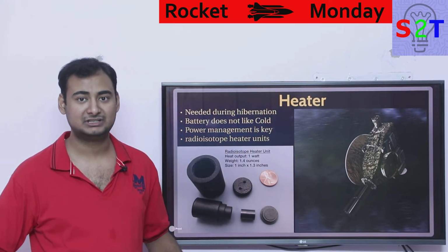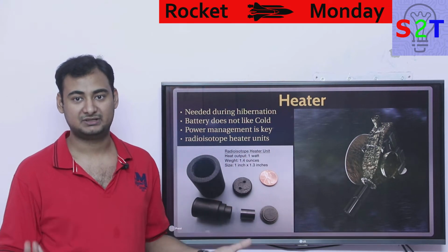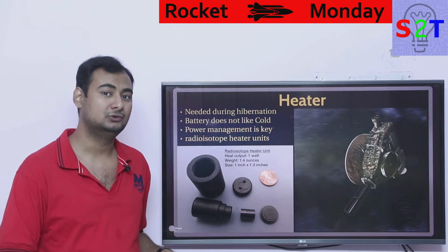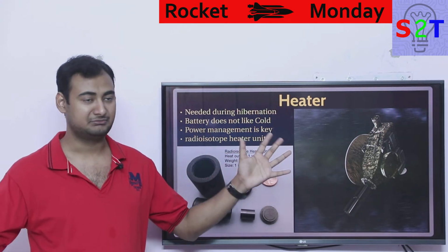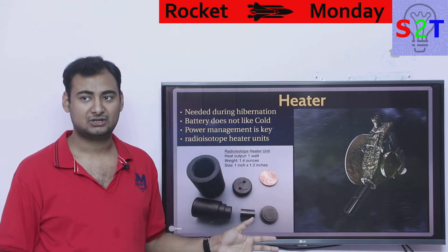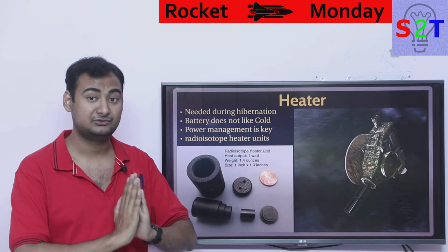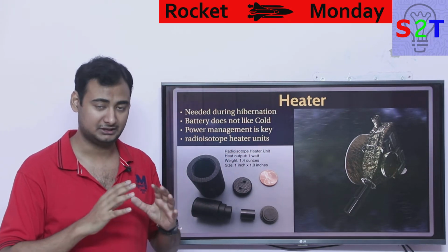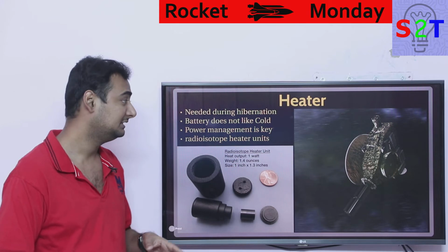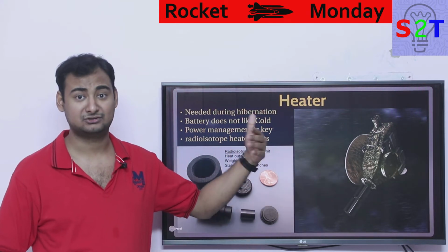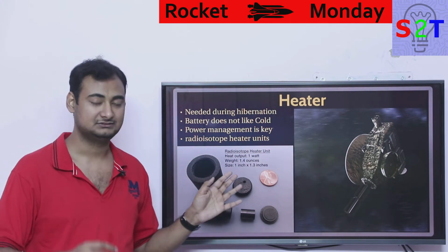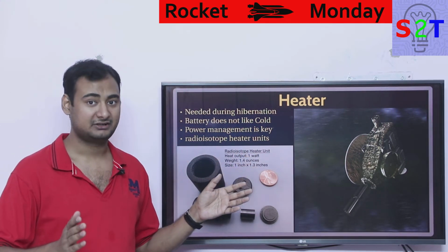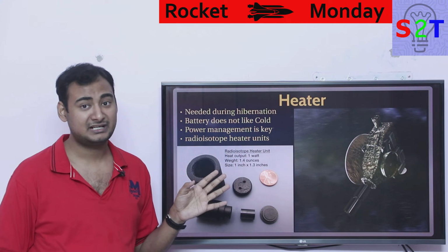Generally, when you are talking about a human or anything big and bulky like a space station, you have to worry about cooling. When you are talking about something low power like a satellite, even though it may have a solar panel of 10 or 20 kilowatts, most of its energy is converted into radio waves. So it itself may drop in temperature drastically. But generally, if the insulation is good enough and you're close to the sun, you don't have to worry about heating. You have to worry about freezing to death. Basically, you don't have to worry about getting rid of excess heat. So power management is the case.